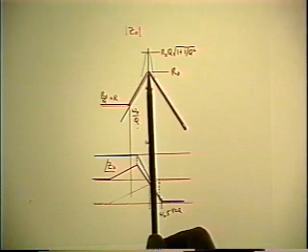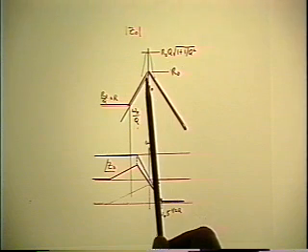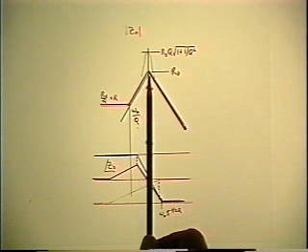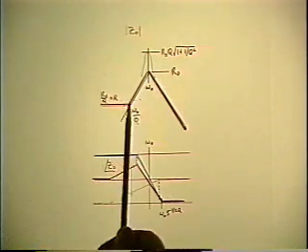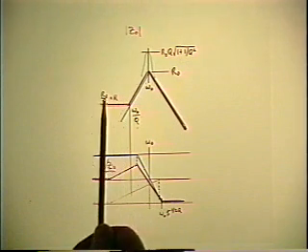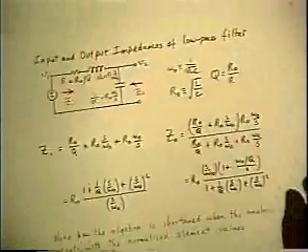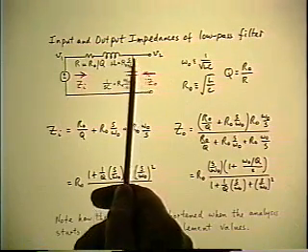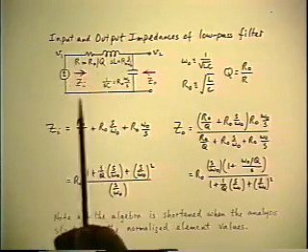Once again, the asymptote intersection is at R0 and stays fixed regardless of the resistance. The resistance determines only the Q, and that determines how high the peak is relative to the asymptote intersection. Notice the interpretation of the low frequency part, where it levels off, is at a value R0 over Q, which is equal to the original resistance, which is, of course, what ought to happen, because looking back into the output with V10 at 0 frequency, the cap is open, the inductors are short, and you're going to see just the resistance R itself.